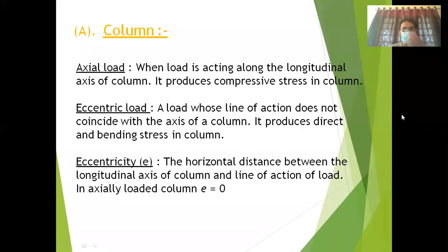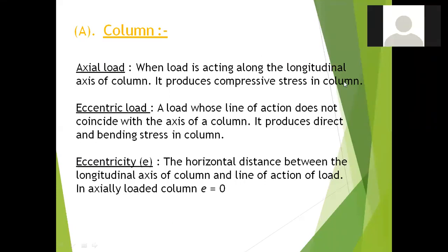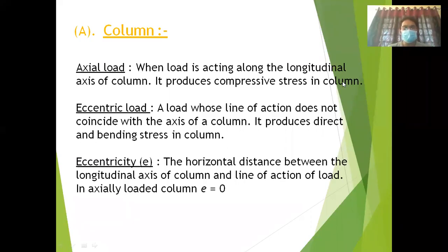A column is a structural element, and in real applications, practically it may not be possible to have an axial load alone. So you have to analyze, or design, your column not only for an axial load, it has to be designed for the eccentric load also. In that sense, this module is very, very important.